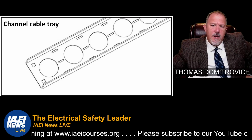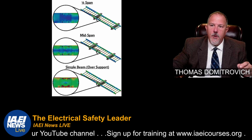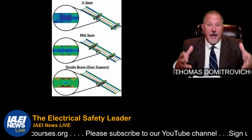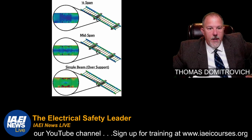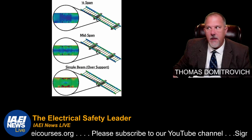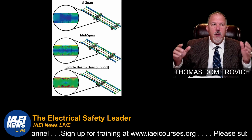Okay, so let's talk about supports, because now in the general application of your cable tray, you have to think about where you're going to split it. Obviously, you can't get an 800-foot run of cable tray. It's going to come in sections, and then you have to put it together. So your standard NEMA lengths for cable tray are going to be in feet, not inches. You've got 12 foot, 20 foot, 24 foot, and 30 foot. Those are the lengths from the NEMA perspective.